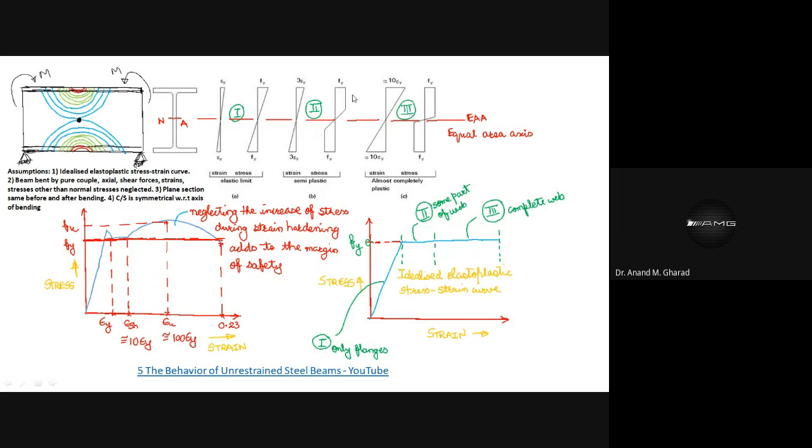Okay, this stress behavior, if it was some non-linear behavior, because you can see in stage 2 or in loading 2, what has happened? The stresses have entered into the web portion, or it has entered into the plastic zone. And because it has entered in the plastic zone, non-linearity can be expected.